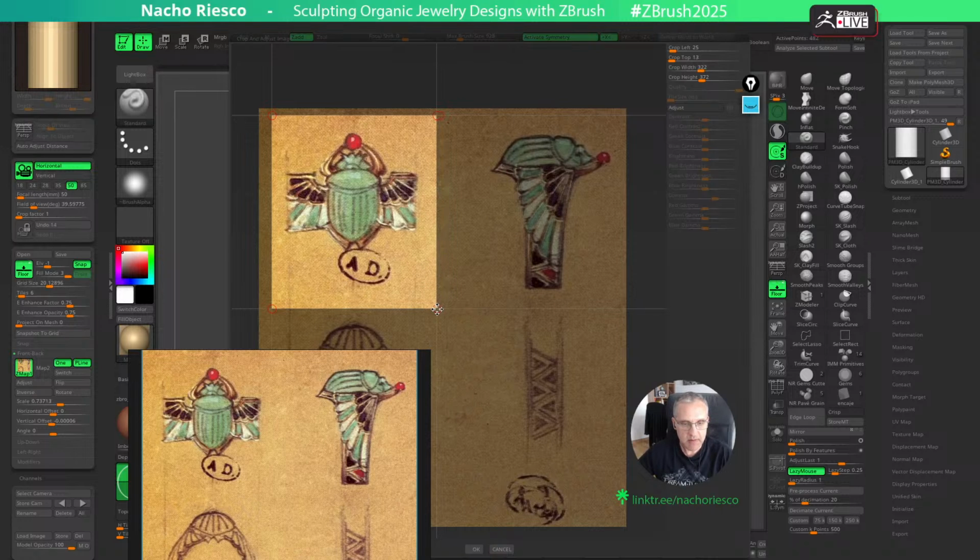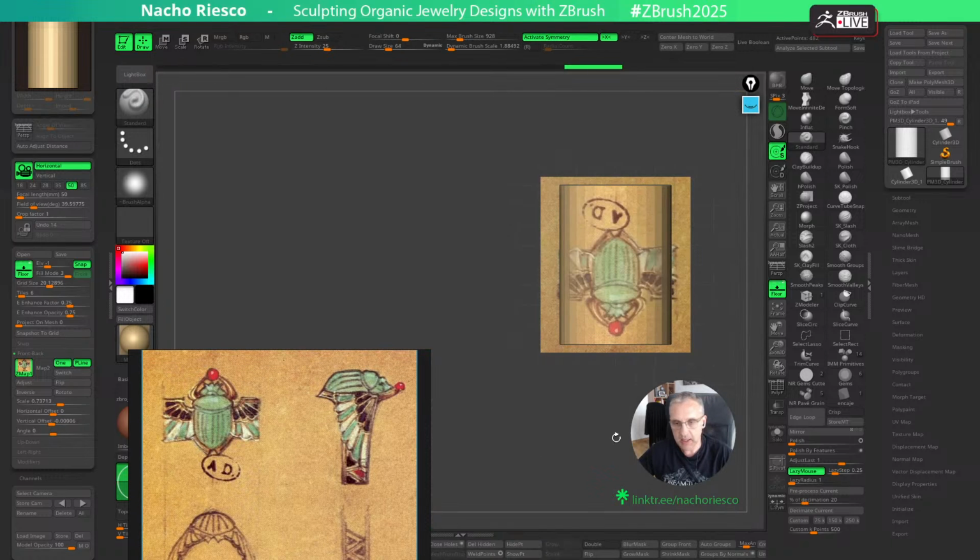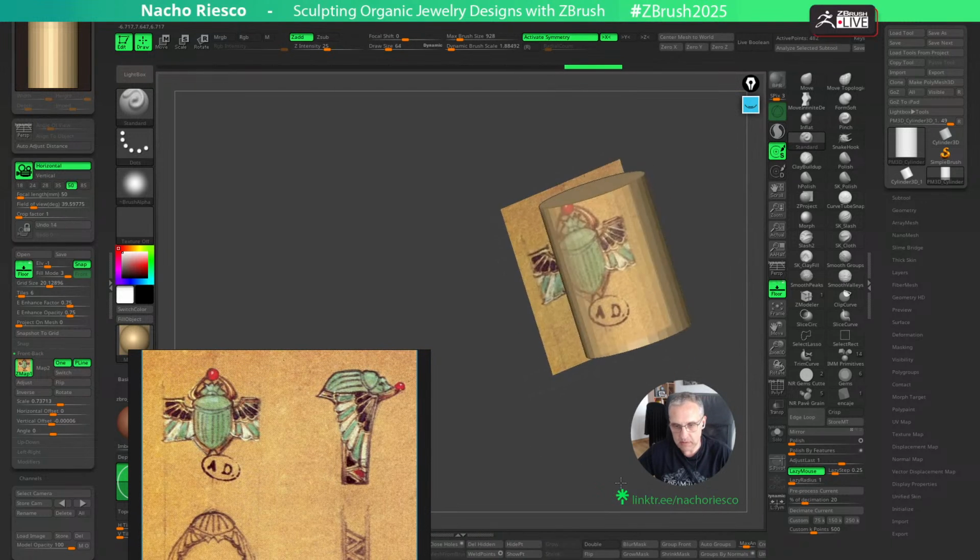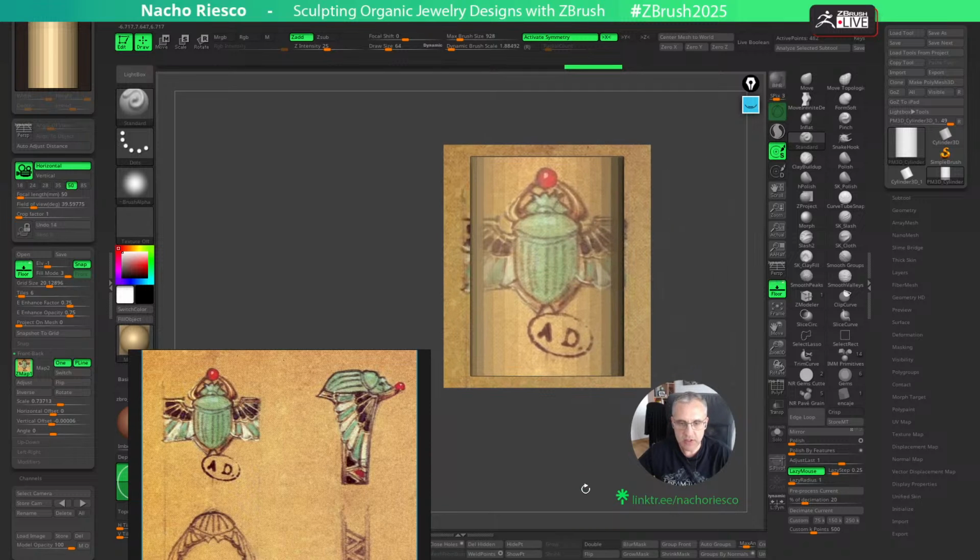So maybe something like this. Let's click on OK, and now we are on the right view. So this is the top view. When I'm working with rings, another extra setting that I make is I turn on the three axes, and I change the elevation from -1 to 0, because all of them are crossed in the middle of the workspace.